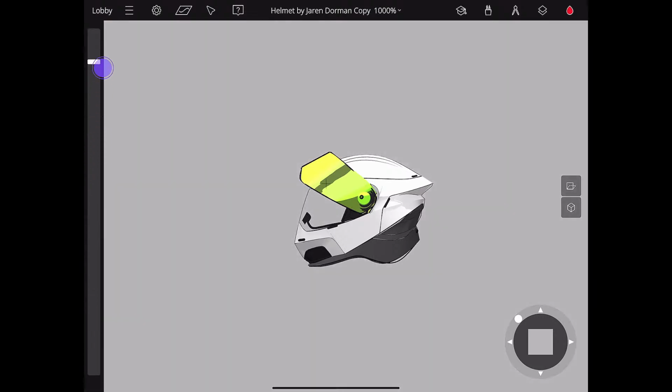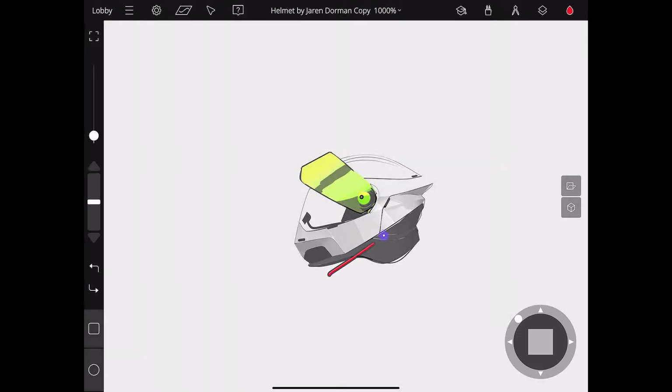I'm going to move the plane this way. So if I draw this curve, we've got these profiles, or these curves, and there are little points like this on each side. I think what you're asking is, can you add points in the center as well? And the answer is no, because a ribbon surface just has two ends to it. It does not have points in the middle.